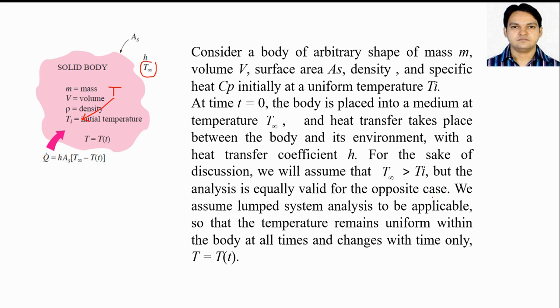You can assume a different case, like casting, where the object is hot and you put this object into a surrounding which is at low temperature. So in both cases, this will work. We assume lumped system analysis to be applicable, so that the temperature remains uniform within the body at all times and changes with time only. That is, T is a function of time only.